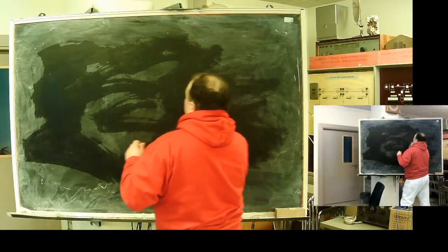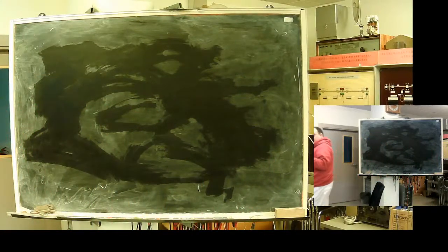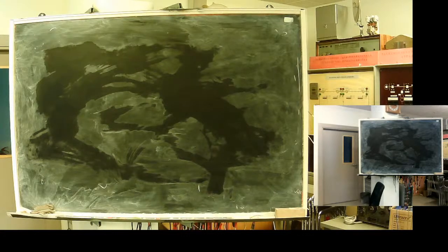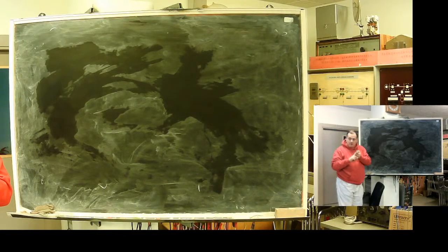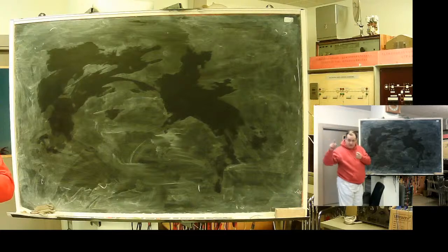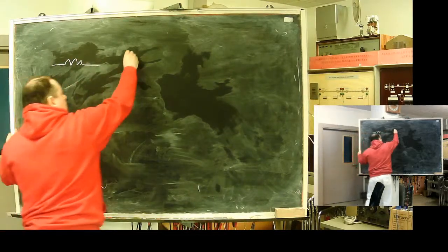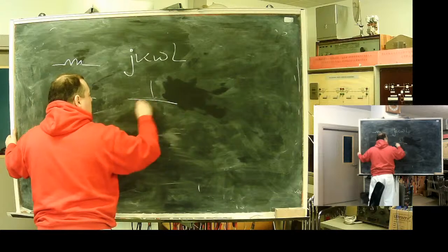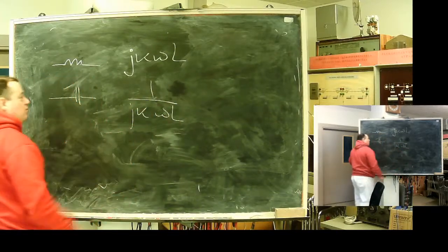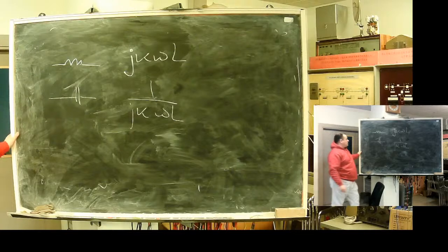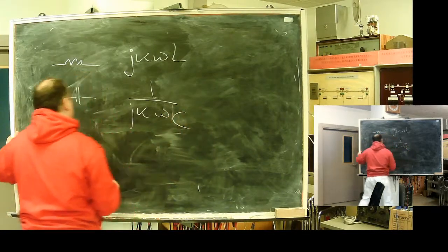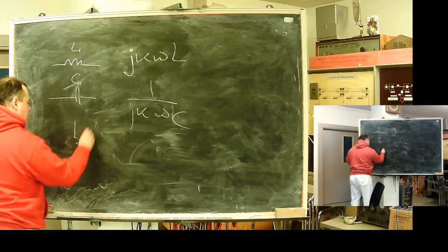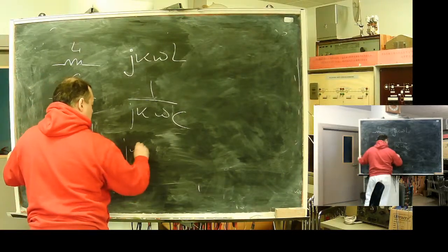We found them right in there. And now, one moment. See, I have K here. For each Fourier row element, the frequency will be K omega. That's why for a coil we write jK omega L. For capacitors, 1 over jK omega C, where K is the number of the harmonic. It should be capacitance. Mutual inductance, jK omega M.